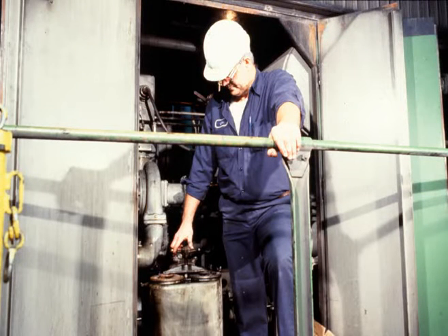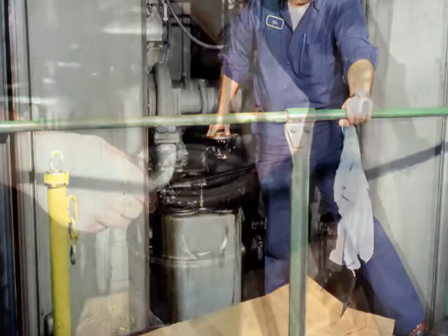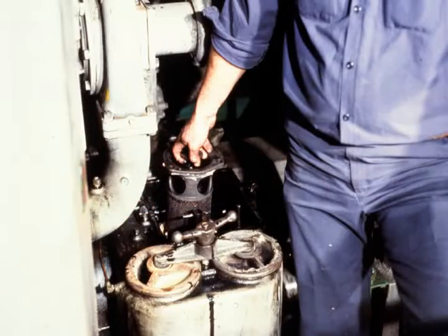Then, remove the star-shaped wheel and clamp to provide access to the main and piston cooling strainers. Remove the strainers and clean them with an approved solvent. Reinstall all strainers using new O-rings and gaskets. Make sure the scavenging strainer is seated firmly against the gasket or a suction leak will occur.